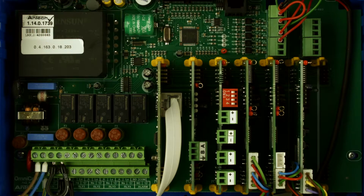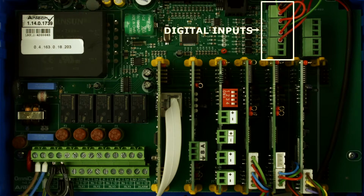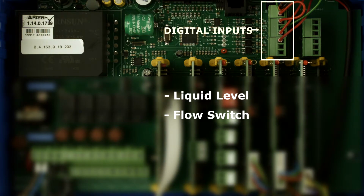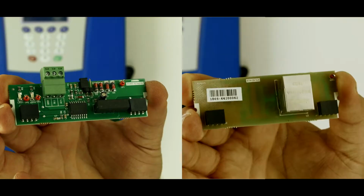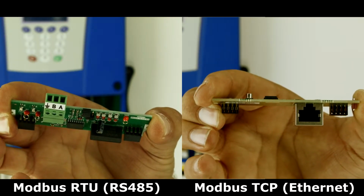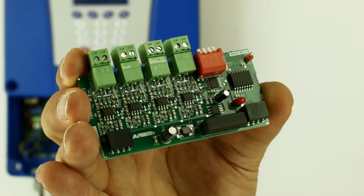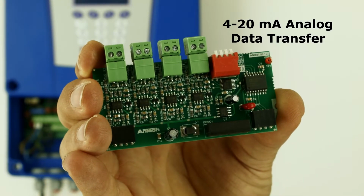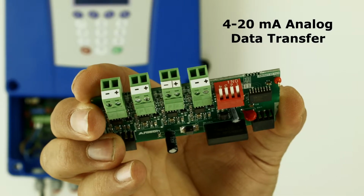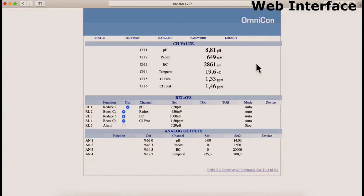Omnicon also has 5 programmable digital inputs. These can be used for liquid level, flow switch, counter, and external alarm. In Omnicon, Modbus RTU and Modbus TCP communication protocols can be used. In addition, the analog output module can also provide 4-20 mA analog data transfer.